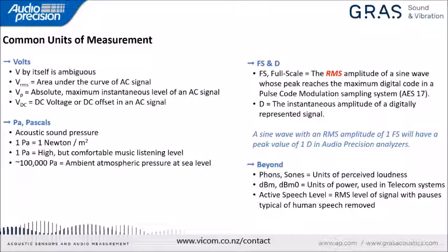This describes, if you will, the area under the curve or the average value of the AC signal. There's a term for this which I learned some time ago. The British used to call this the heating power of a signal. And what it meant was if you have a certain value of volts RMS and you connect that to a resistor, how much will it heat that resistor up?